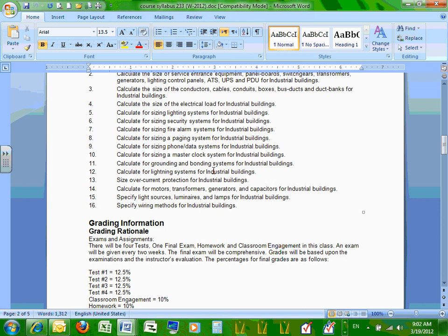If anybody, Dustin, my friend, asks you what wiring method is preferred in an industrial plant, you should come up with two or three ways of wiring in an industrial environment. You're going to ask, is it a hazardous location? Is it Class 1, 2, or 3? Do I need seals? Do I need explosion-proof equipment? Do I need a bus duct? What's the best way of wiring a manufacturing floor? Should I use a bus duct? Yep, a great way of doing a manufacturing floor is a bus duct.